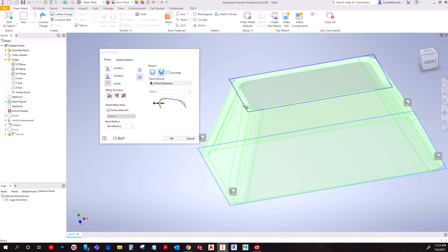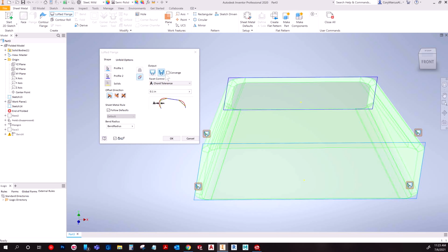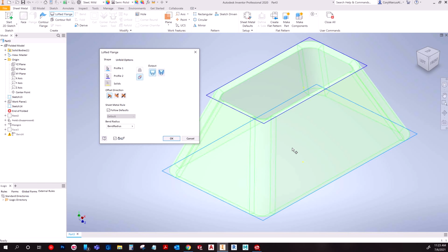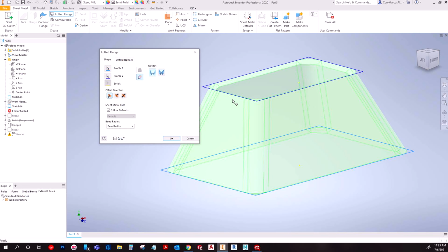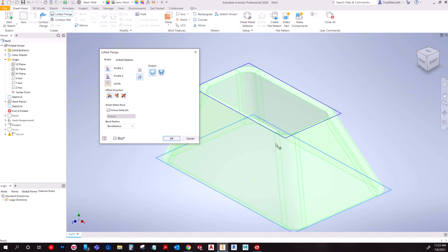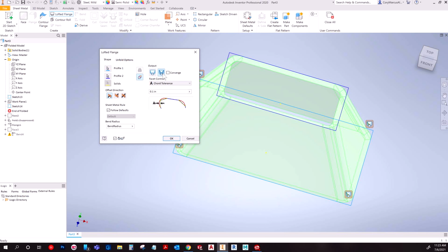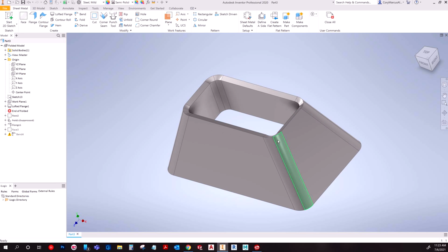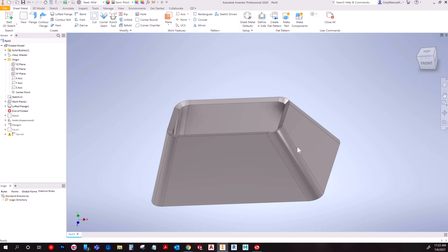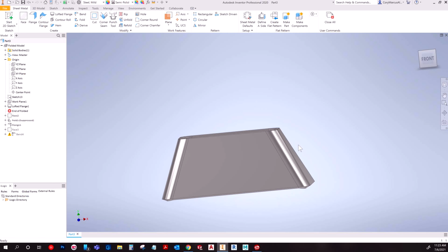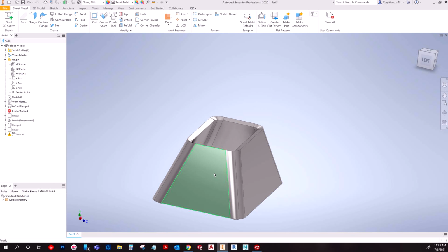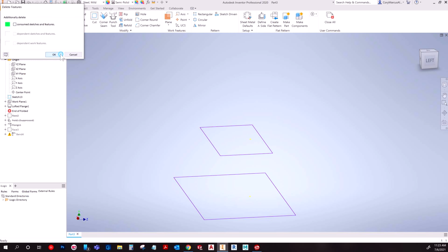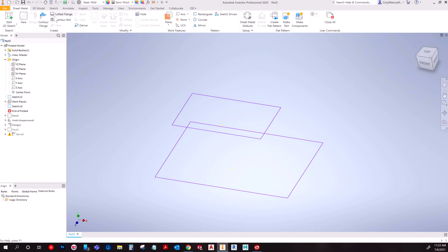There is one thing that I always suggest doing, and it's this: change it to die-formed. I guarantee you, where you work, they're not making this with a press brake, but they may be. Now you don't know what that means, but basically the difference is die-formed means it's rolled. You can see it looks very smooth. It only has a few edges. When I do press brake, I'll just hit OK and I'll undo it, but what that means is they're actually taking it and folding a piece of plate flat, like as if you were bending it, like making that L-shaped kind of style plate. They're going to do it every single piece. They're folding it manually, which is really freaking hard to do. So I really doubt they're doing that, but at my old job they did do quite a bit of that.